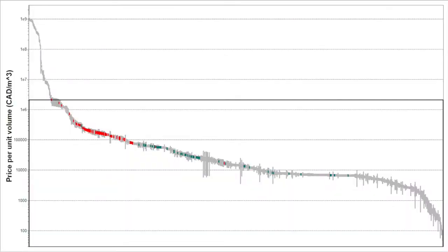To begin, it was determined that the cost of the shackle should be less than $25 per shackle. In material selection, the cost is priced per meter cubed. If the shackle was 15 centimeters long and 1 centimeter in diameter, to stay within the specifications, the cost per meter cubed would need to be less than $2.1 million.